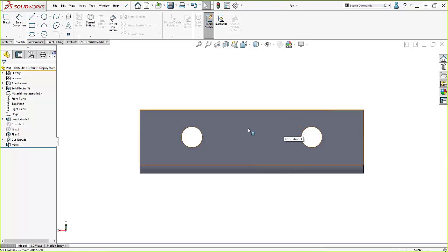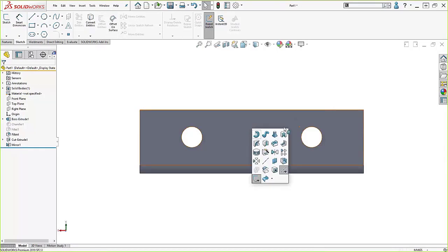So I exit the sketch, and I go to the S button again, and these are the features that are in my S button to help me create new things. Like I can actually turn on and off axis, I can add an axis, I can do all of these different features from this S button. So it's very similar to the mouse gestures in that you have the multiple contexts for the S button, the shortcut bar. You've got sketches, parts, assemblies, and drawings, and they're all separate, and they don't overlap. They just come up specifically when you're in that particular context.